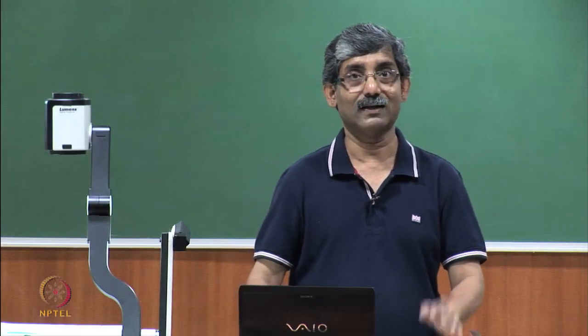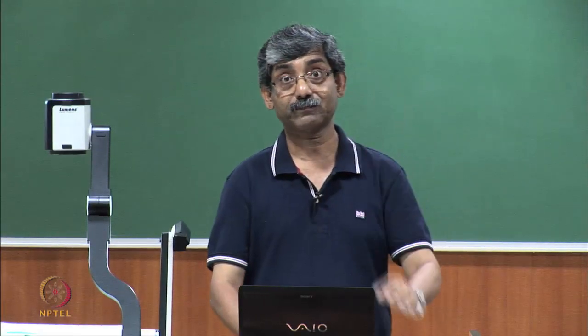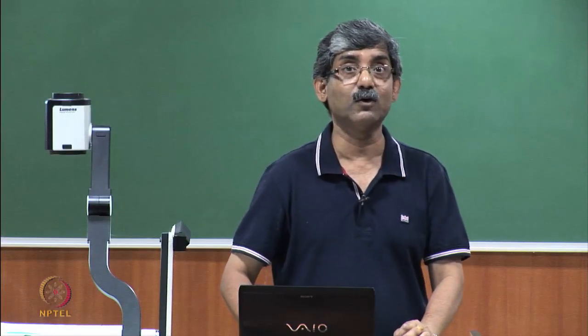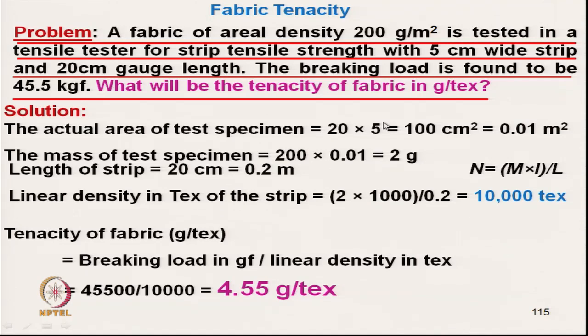Okay. So, to compare the breaking tenacity, the strength of the fabric, we should compare in terms of tenacity of the fabric, in terms of gram per Tex. So, here the idea is, first you have to get the value of Tex of the strip, and then we can calculate.